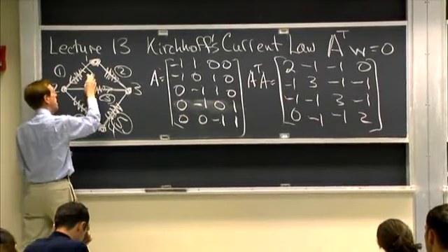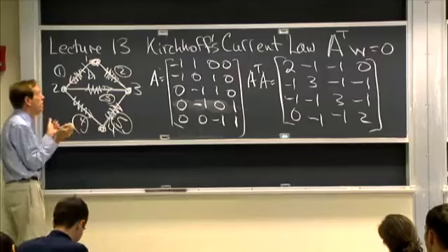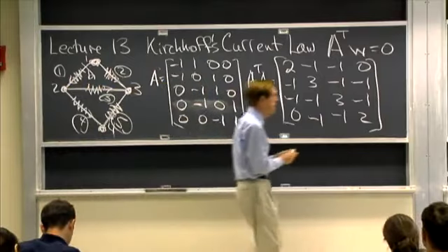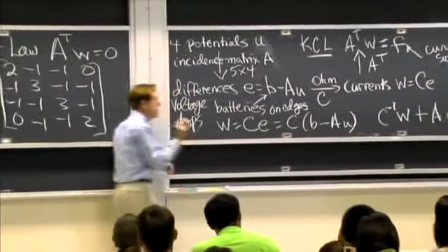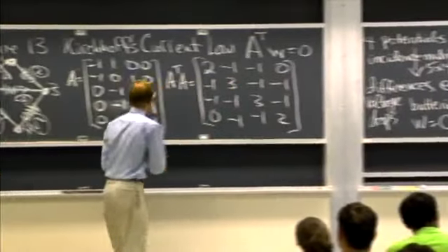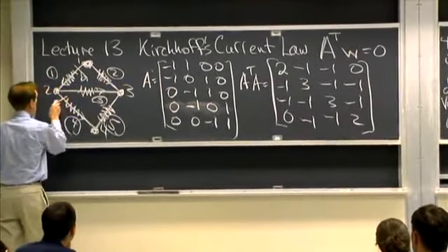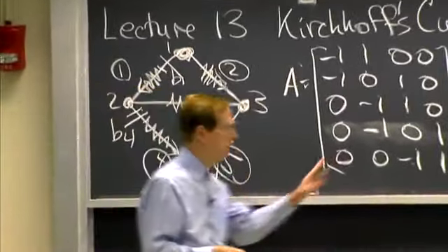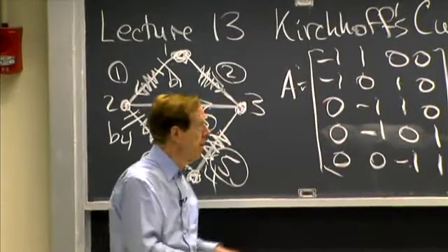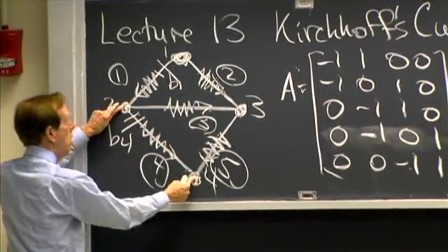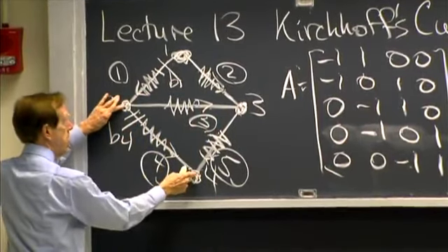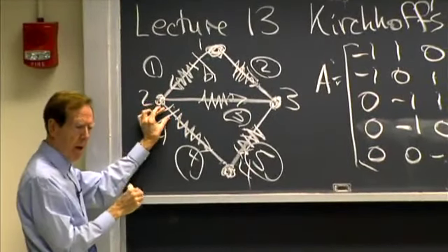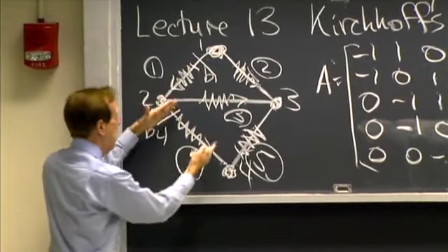But there's a battery in there, B1, of voltage, say a 9-volt battery, B1 would be 9. Depending on how it was placed in there, the B here would be a +9 or a -9 in the first component. And if I had another battery on edge 4, there would be a battery B4, and that would show up in Ohm's law, because Ohm's law looks at the difference in these potentials, but also accounts for the battery.